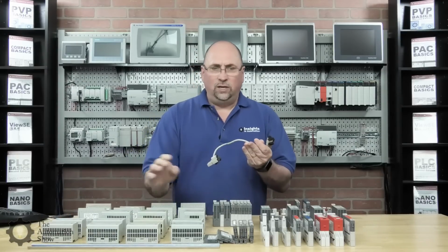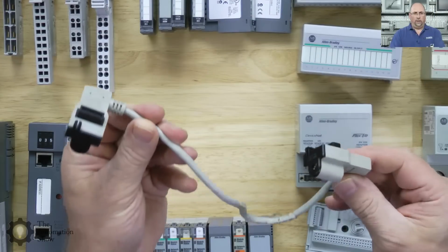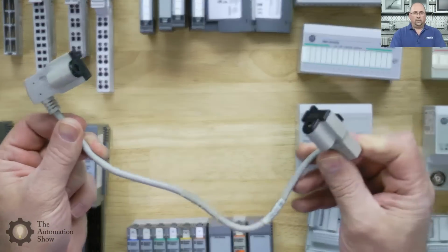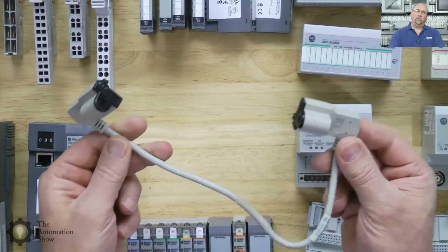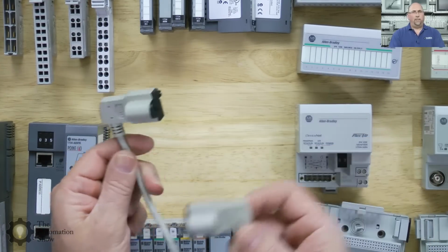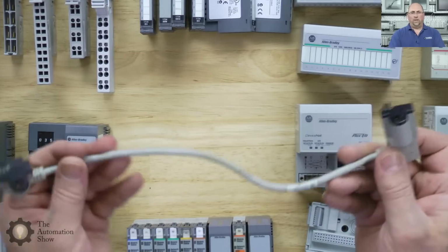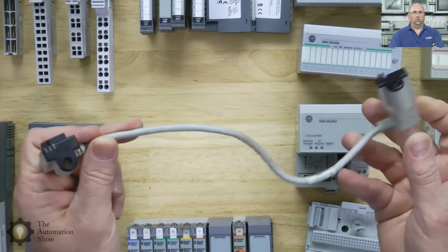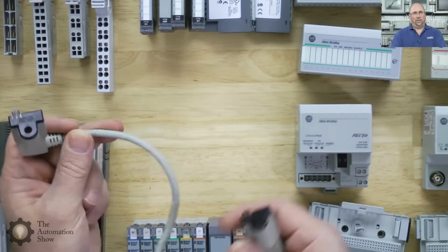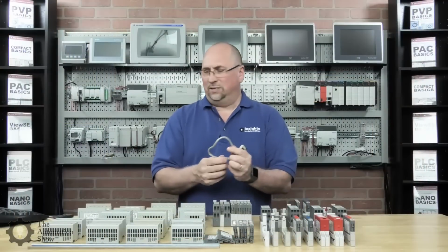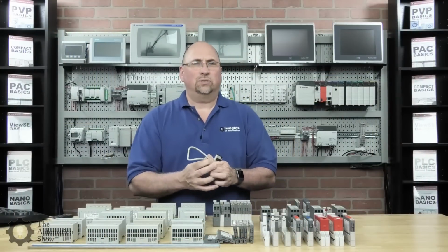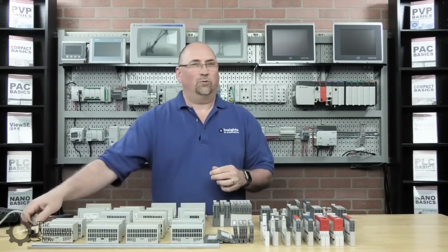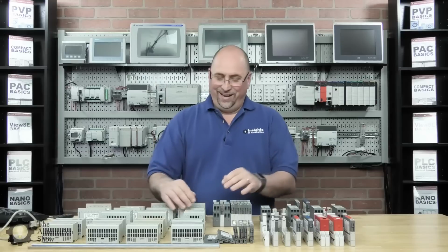racks of each of these lines with what we call an extension cable. This is kind of popular with the Flex-IO, not very popular with the Point-IO, because the Point-IO cable, you see how thin this cable is? The Point-IO cable also carries power, so it's really thick and doesn't have a great bend radius. I know somebody who bought one of them, and they just threw it away because it was so hard to work with. So while they both have extension cables, the one for the Point-IO just doesn't seem to be very practical for